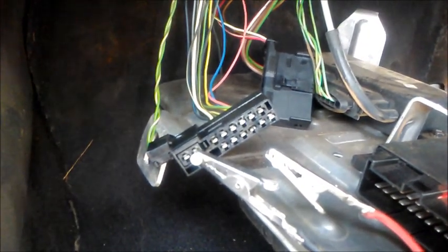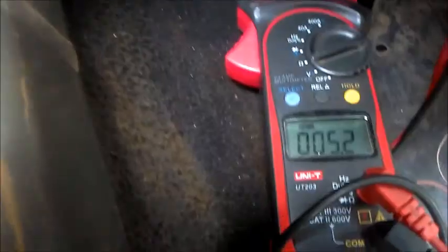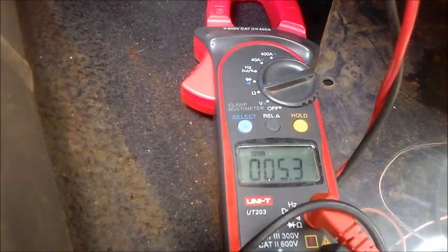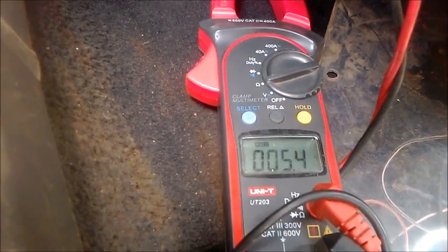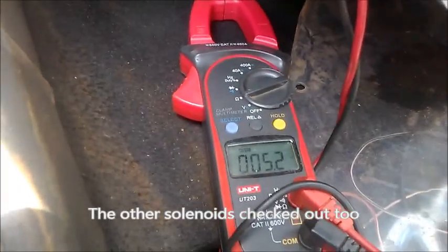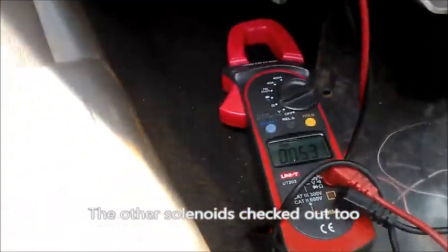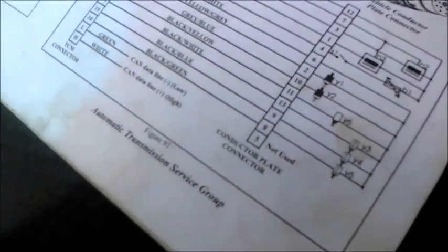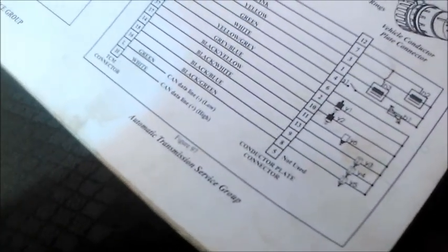Okay, now I'm on the terminal of solenoid Y4. It reads something very similar to solenoid Y3 that we started with. So I guess that is also fine. Then the next one is on terminal 16, according to this. If you look at that schematic, it is on terminal 16.